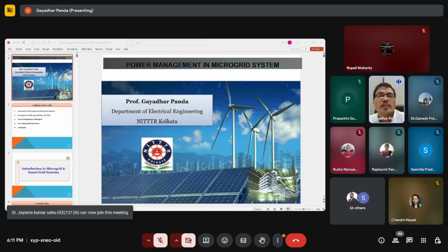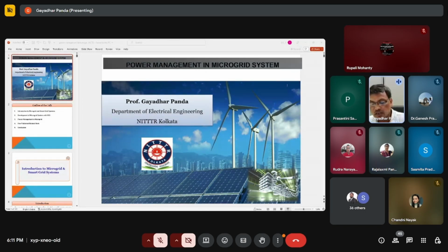And this is solar energy, where you know how the solar cell produces power. These are rooftop solars. You know very well these are clean sources of energy that produce power. The solar array output is a DC voltage, then you use converters like a DC to DC boost converter, then inverters for integration to the grid.